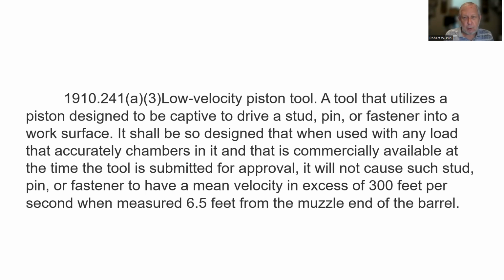Low velocity piston tool, a tool that utilizes a piston designed to be captive to drive a stud, pin, or fastener into a work surface. It shall be so designed that when used with any load that accurately chambers in it and that is commercially available at the time the tool is submitted for approval, it will not cause such stud, pin, or fastener to have a mean velocity in excess of 300 feet per second when measured 6.5 feet from the muzzle end of the barrel.